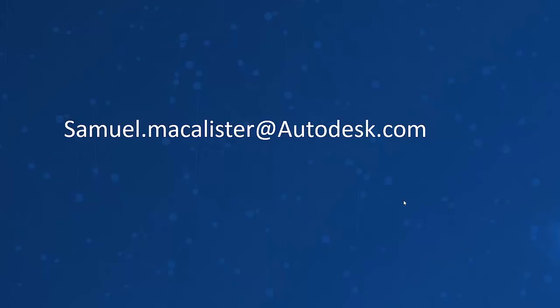So Praveen, can we link CAD files in a cloud environment? Yes, if it is using the BIM 360 Design or C4R tools with Desktop Connector. As far as I'm aware, I don't believe you can do another AutoCAD workflow of linking CAD files, possibly with AutoCAD 360, but I haven't done a deep dive on that product. So within this space, it's via the Revit tools and working with CAD files linked to Revit.